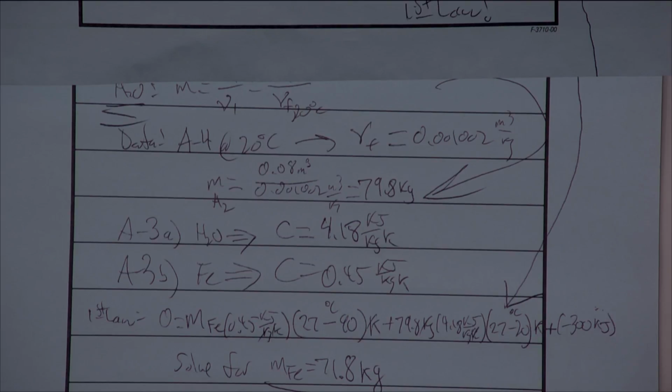Believe it or not, we're done now with Chapter 4. We've finished looking at the theory and all the example problems I'm going to look at regarding closed systems. And now we're going to start dealing with the open systems, which are also called control volumes. So we're making a fundamental change now in the types of problems. The types of problems that utilize our closed system analysis are constant mass problems typical of sealed containers, right? Piston cylinder devices, rigid vessels, balloons, bags, anything that is sealed would be a closed system problem.